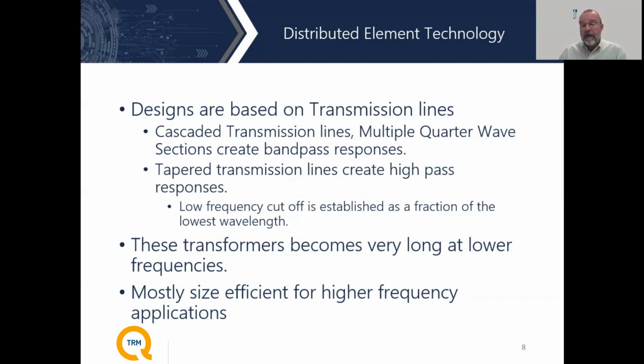It is really more of a higher frequency sort of application. The other thing also that is different from lumped element technology: instead of being an all pass sort of design, these devices tend to be band pass designs, which means that there's a definite upper frequency and a lower frequency. There are some exceptions where we make high pass structures, where we start running into limitations of the high pass, again with moding happening, that limit the high end. But there are definite advantages to distributed technologies that are certainly different than what we have for lumped element technologies.